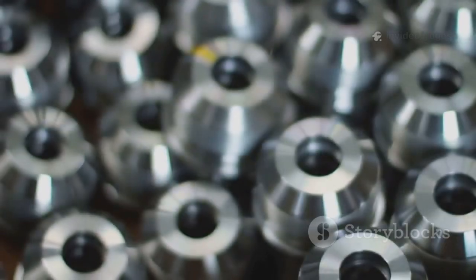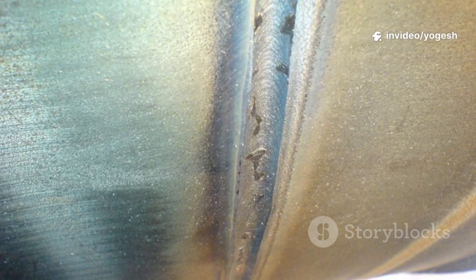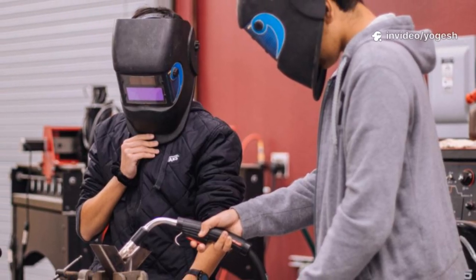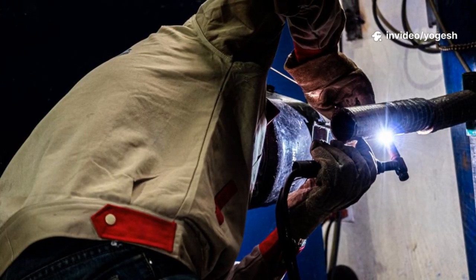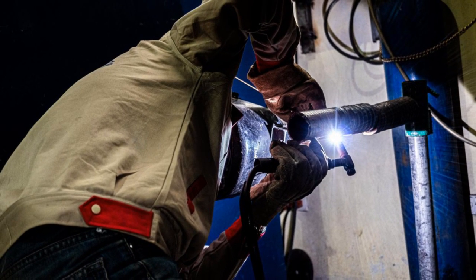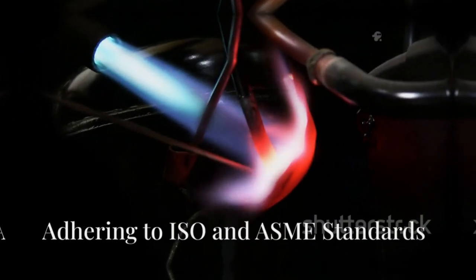To ensure a flat mounting surface, a flat contour and G-finish symbol are added above the fillet weld. This single, combined symbol communicates groove and fillet welds, all-around extent, and finishing requirements. The result: clear, unambiguous instructions for a robust, precise assembly. Advanced symbols turn complex requirements into simple, actionable drawings. This is the power of mastering welding symbols.